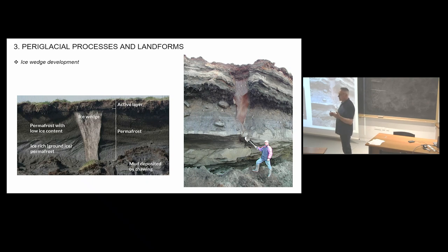Since the glaciation, we have formation of these ice wedges, and we're capturing water, transforming it to ice, and it's sealed there. We had that for, let's say, 12,000 years. Now we're melting these ice wedges, we're thawing the permafrost, and you can imagine, of course, if you thaw, you melt this thing here, the subsidence that occurs, the depression you create, the water that goes in it, the convection that goes with water, and then we go. So there's a positive feedback to permafrost degradation.